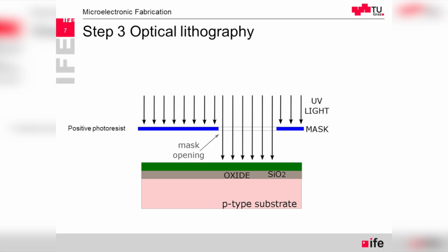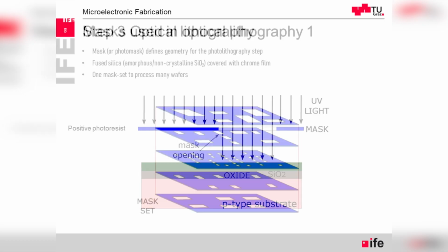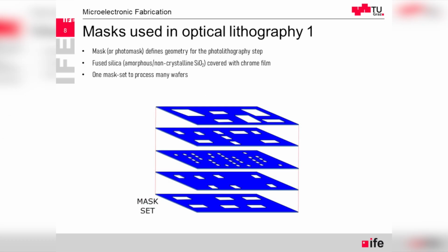So then there will be removal of the photoresist, there will be removal of the oxide, and then we will create an opening window to introduce implants of the N-type for the P-type transistor. But slowly, before we get there, I would like to stop at this really important process, photolithography. It happens for each layer.